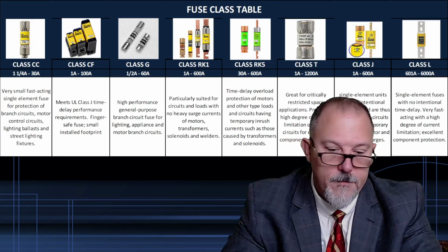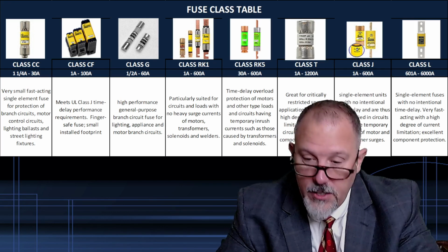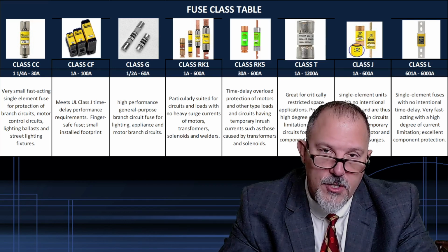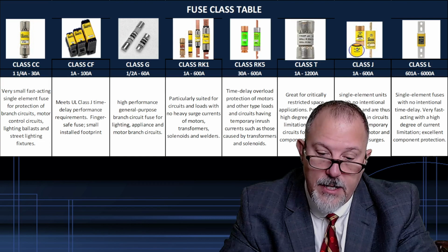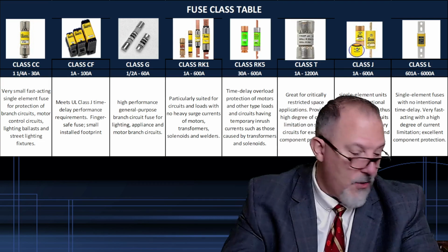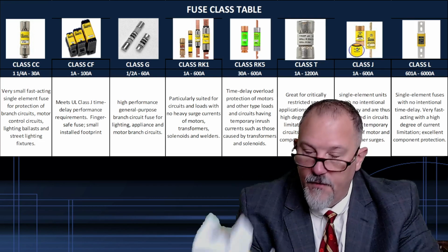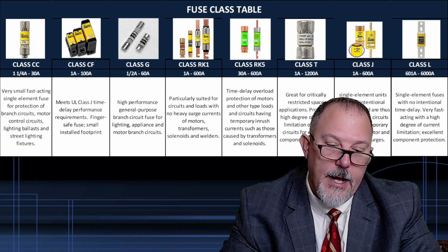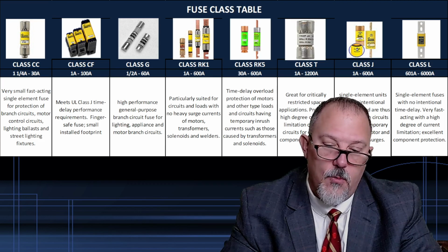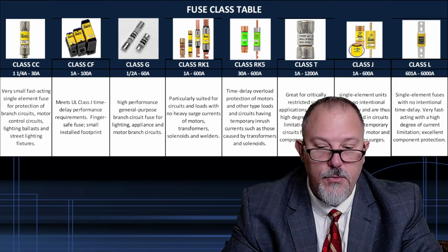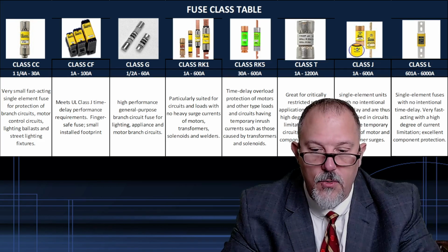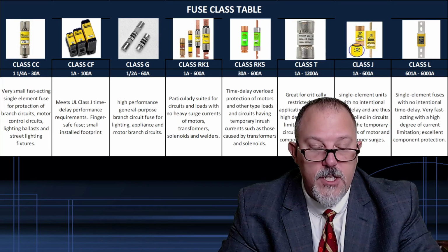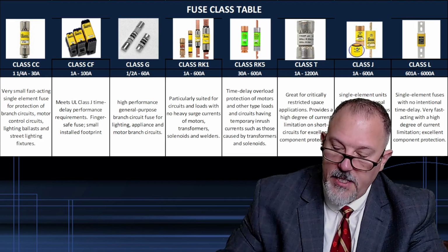So what we know is, just like a circuit breaker has frame ratings, fuses will have sort of frame ratings. And they pretty much align with the switches and whatnot that they will go into. Remember, we said we have holders, and a typical fuse holder will handle a range of fuses. For example, this is a 100 amp fuse, and it won't just hold a 100 amp fuse. It can hold fuses rated lower than 100 amps. So the size of the fuse will be different.